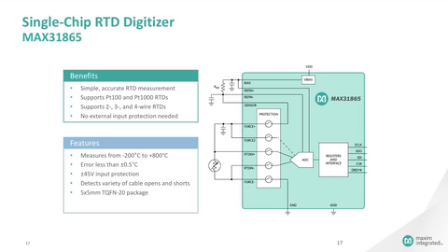The device measures the resistance of the RTD by forcing a voltage across a series combination of a reference resistor and the RTD. The voltage on the reference resistor acts as the reference for the internal ADC. The voltage across the RTD is then what is being measured. Therefore, the data out is the ratio of the RTD resistance to the reference resistance. The corresponding temperature is calculated from the value of the RTD resistance.